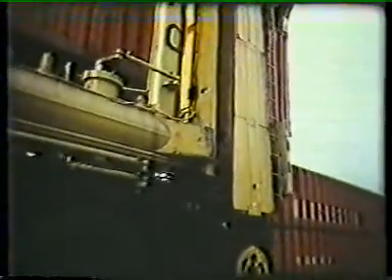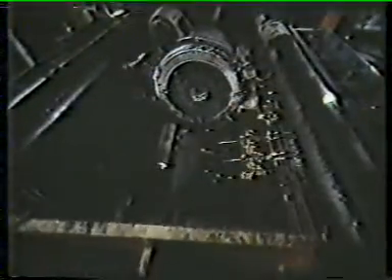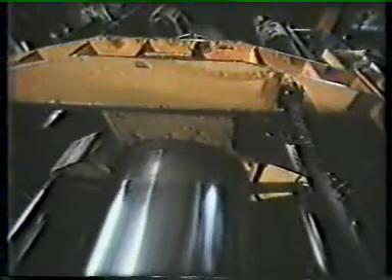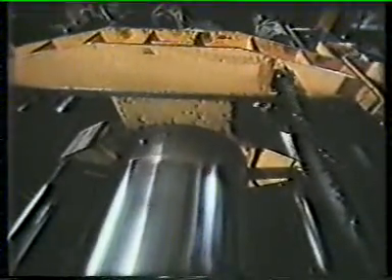The transmission of hydraulic power is divided into two parts, hydrokinetic and hydrostatic. Hydrokinetic systems depend on the use of the hydraulic fluid as a vehicle of kinetic energy. The velocity of the moving fluid provides the power. Hydrostatic systems are those in which the primary function of the hydraulic fluid is transmission of force and power by pressure. This film is concerned with hydrostatics.